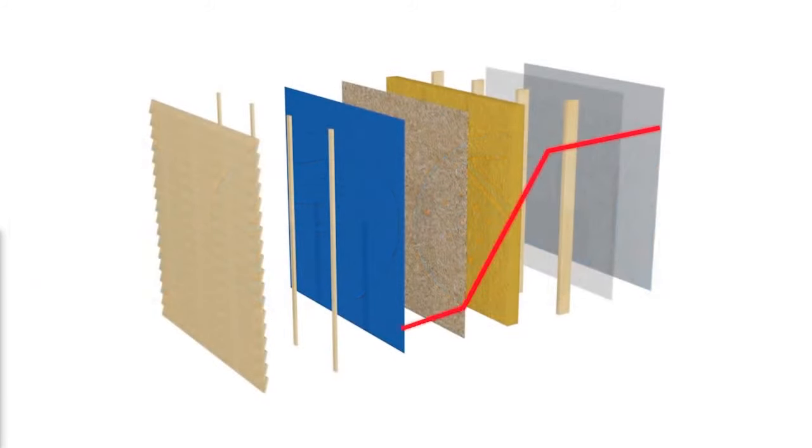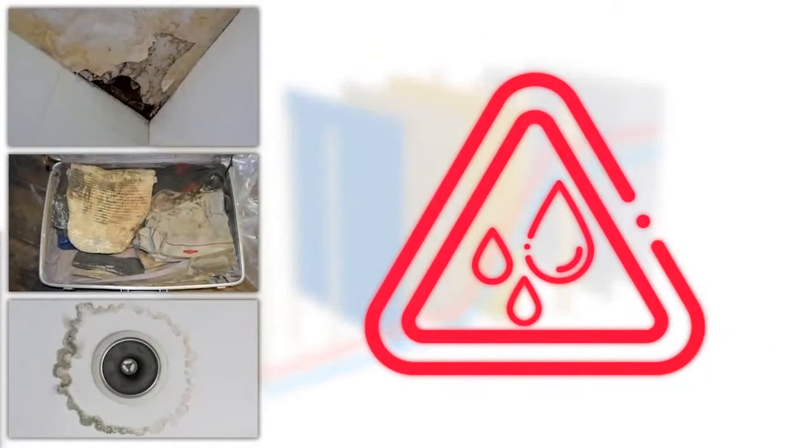The insulation in the building fabric helps keep the indoor temperature more or less constant, but as we move outward through the building element, the temperature will drop sharply across the insulation layer. As the temperature drops, the air loses its ability to retain water vapour. At a certain temperature, called the dew point, this air loses its ability to retain the moisture, and the moisture condenses. In our bathroom mirror example, this is inconvenient but pretty harmless, but say in a roof space, this liquid can cause timber to decay or damage any stored items.